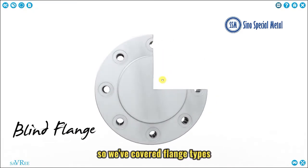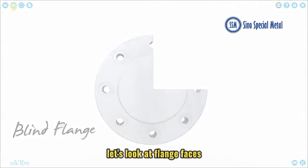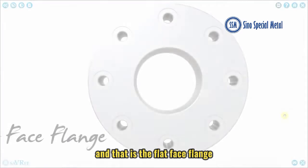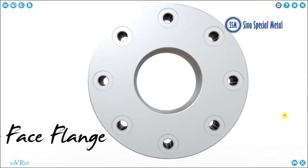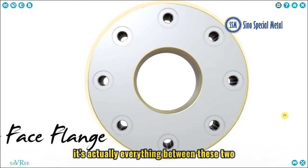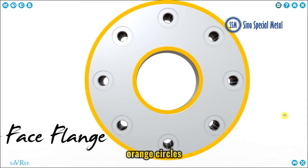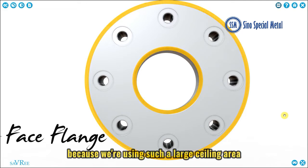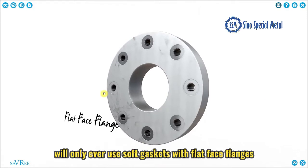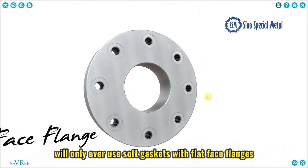So we've covered flange types. Let's look at flange faces. We'll start with the most simple, and that is the flat face flange. The flat face flange has a large sealing area. It's actually everything between these two orange circles. Because we're using such a large sealing area, we'll only ever use soft gaskets with flat face flanges.